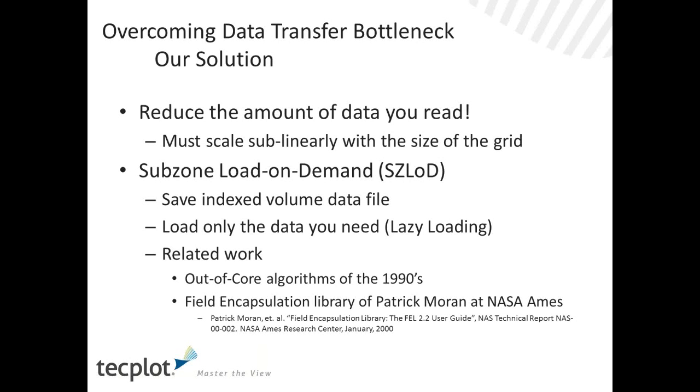It looks at the fact that, for instance, for a slice, you need to read very little of that file in order to create that slice. Right, you only need to read the data near the slice plane. And so if you have some sort of an indexing into the file that tells you that these pieces of data are close to the slice plane, then you can just read those pieces of data, and that's exactly what Subzone Load on Demand is.